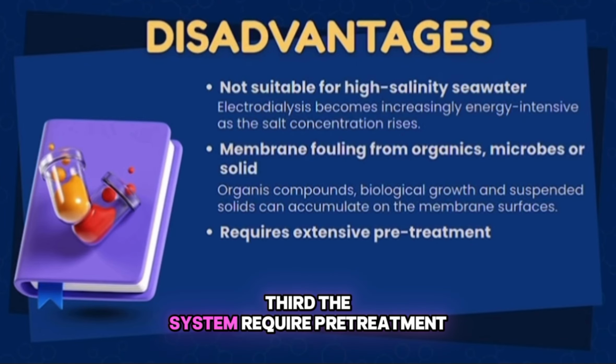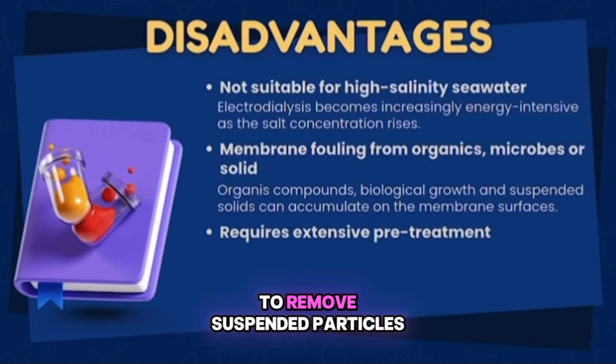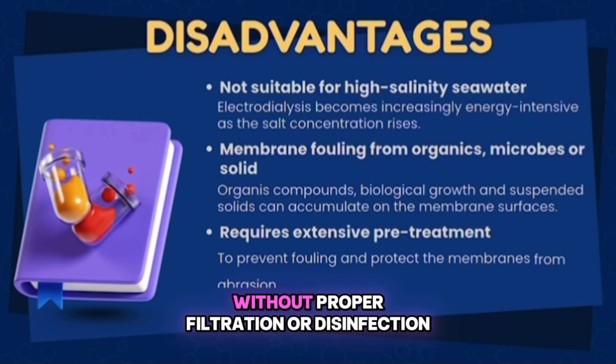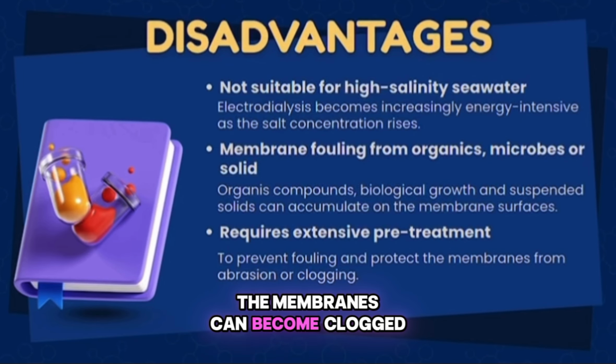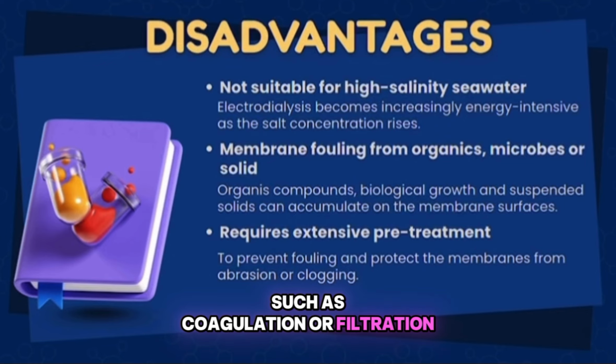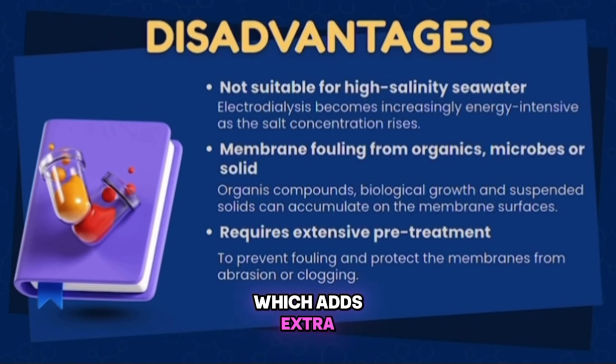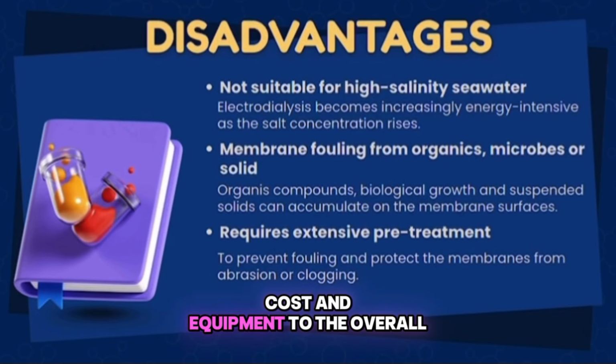Third, the system requires pre-treatment to remove suspended particles. Without proper filtration or disinfection, the membranes can become clogged or damaged. Therefore, pre-treatment steps such as coagulation or filtration must be carried out, which adds extra cost and equipment to the overall treatment process.